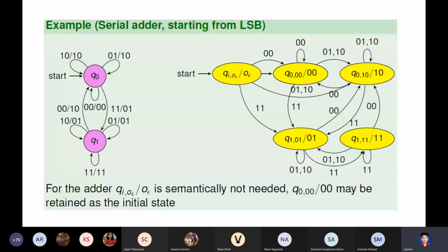Okay, so let's assume that this is the Mealy machine. It is already discussed in the class. So let's see how Q naught behaves. Let's look at the incoming edges to Q naught. Q naught has one self loop where the output is 1, 0. So let's see what are the possible outputs when one transitions to Q naught.